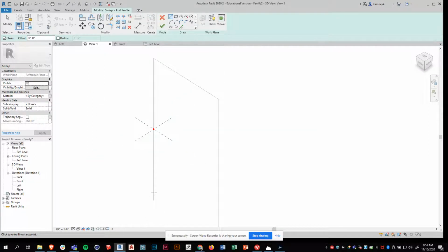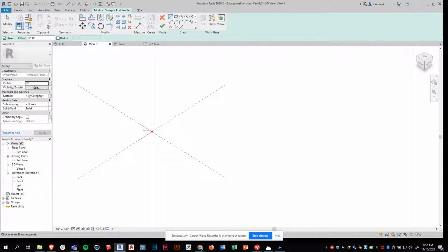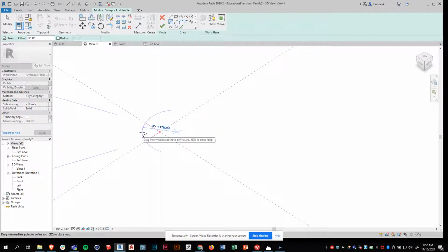Now you have to think about how you want it to relate to the line. So here's what I'll do. I'm going to go 2 inches this way. Already seems huge. I'm going to go 2 inches this way. In fact, I'm going to cut that in half. I'm going to delete it. Delete those. And let's just do 1 inch. And then I'm going to go to this tool here, start end radius. I'm going to click here, here, give it something like that.